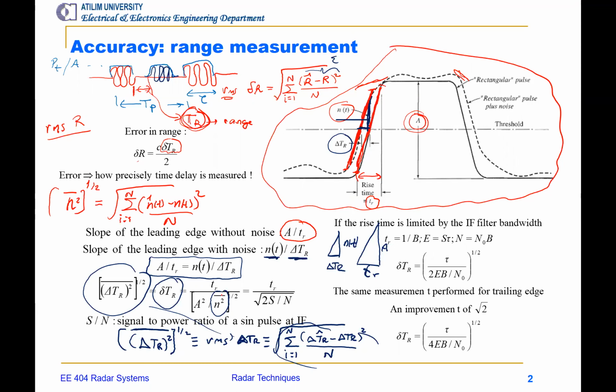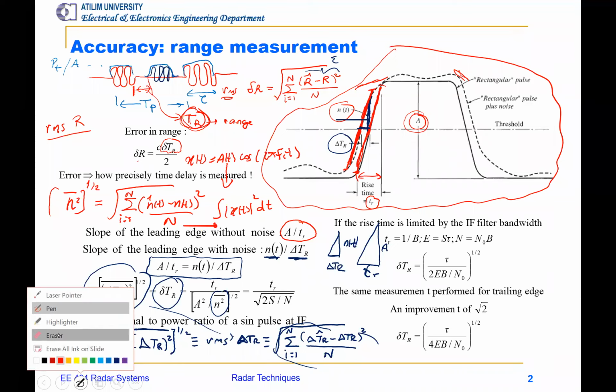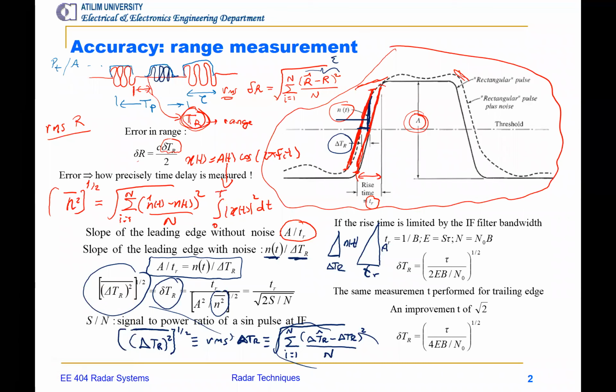Okay, we can write the signal power and amplitude relation by using a cosinusoid. Let's take, for example, x of t equals a of t cosine 2 pi fc t, and then get its power. It's going to be the integral of x of t magnitude squared dt from 0 to the period T, and the power is going to be a squared over 2.